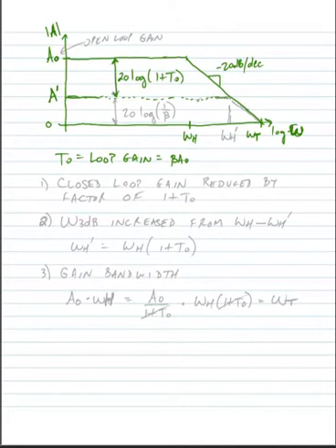The distance from 0 dBs up to this point, A sub 0, is equal to 20 times the log of 1 divided by beta, our feedback factor. Once the line hits the frequency response of the original amplifier, it follows it. So we see a new pole frequency, which we'll call omega h prime.